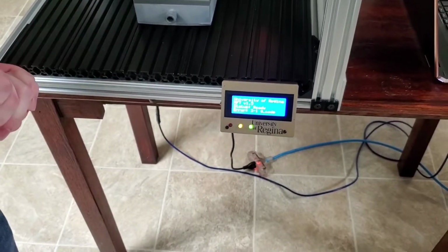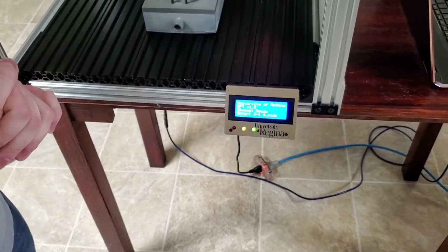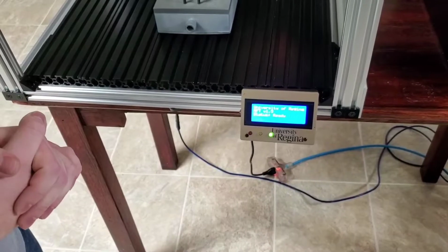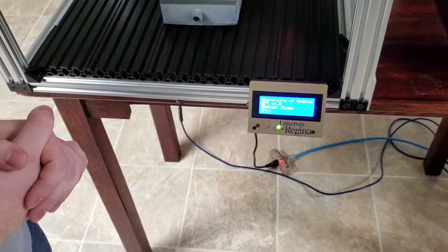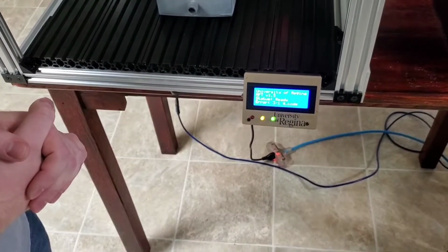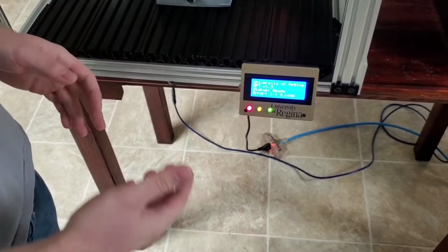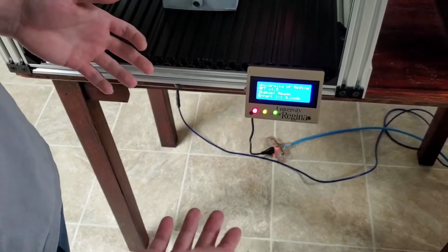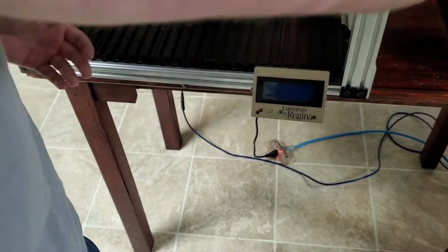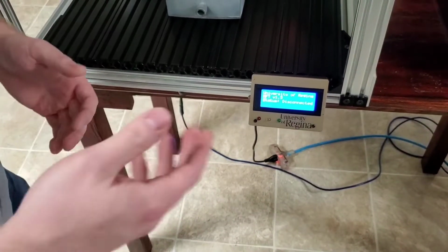Now, if we go ahead and send repeated bad G-codes, and again, now you can see it's fatal. So we've gone red. This now is not able to recover, so we're going to have to do a full reset. So by powering it off, powering it back on, we're in that initial setting.